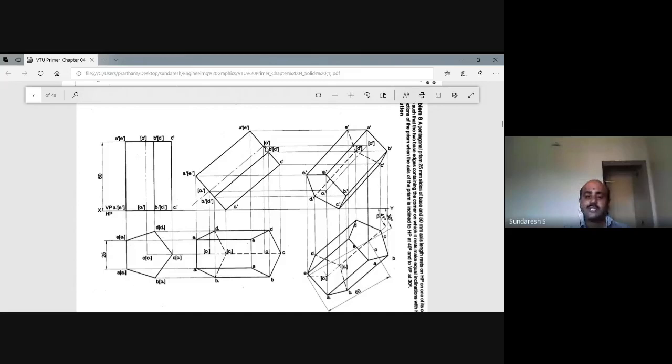Now the axis is already inclined to HP at 40 degrees. In the same position, you are tilting the solid such that the foreshortened axis makes an angle of 30 degrees with respect to VP in the third position. Since the foreshortened axis is tilting with respect to VP at 30 degrees, the angle at which the solid is actually inclined is not exactly 30 degrees; it is more than 30 degrees.